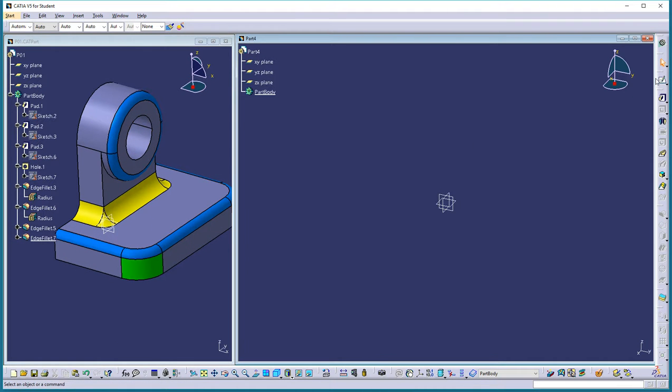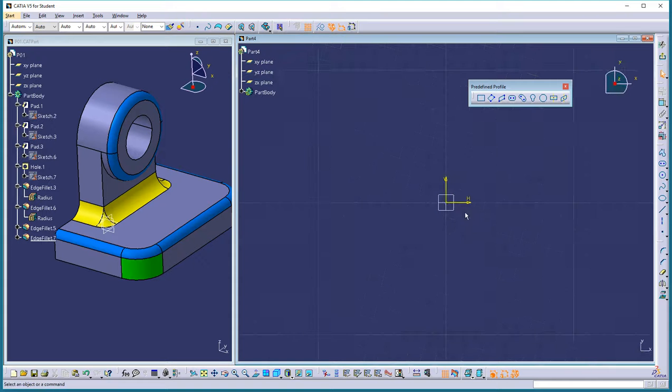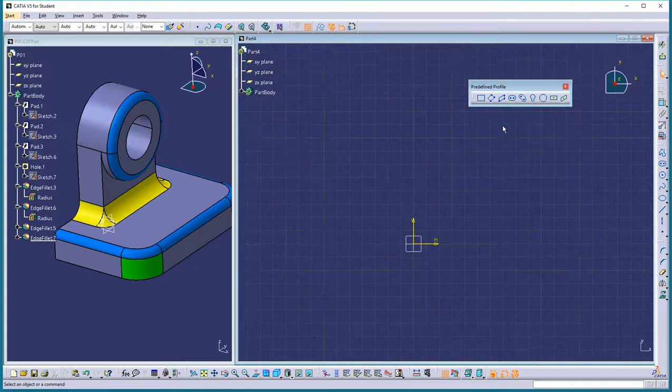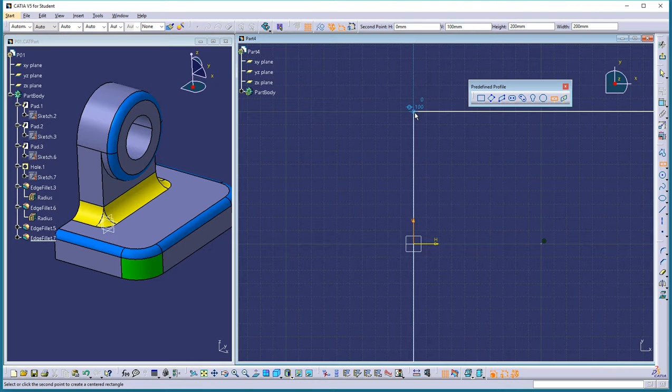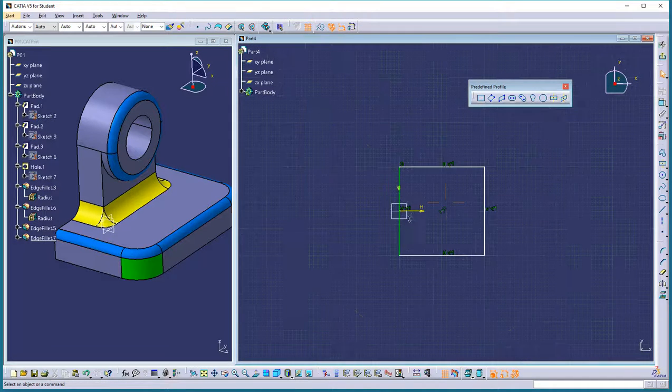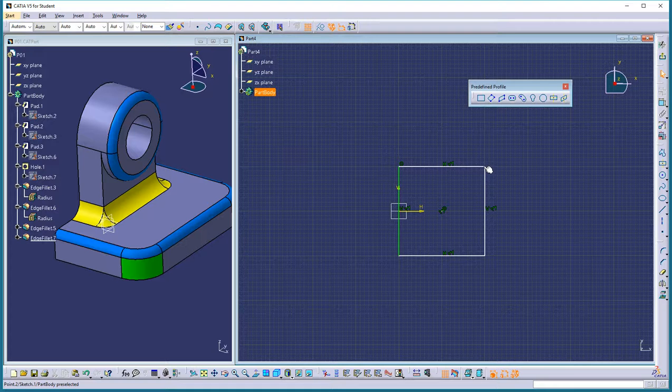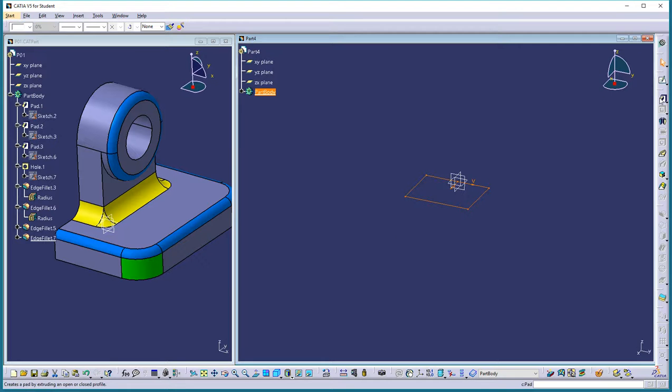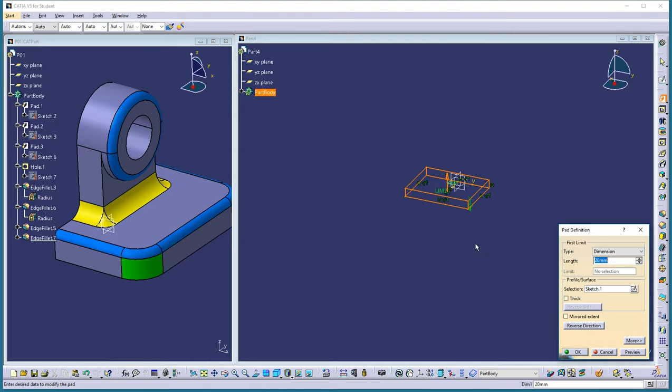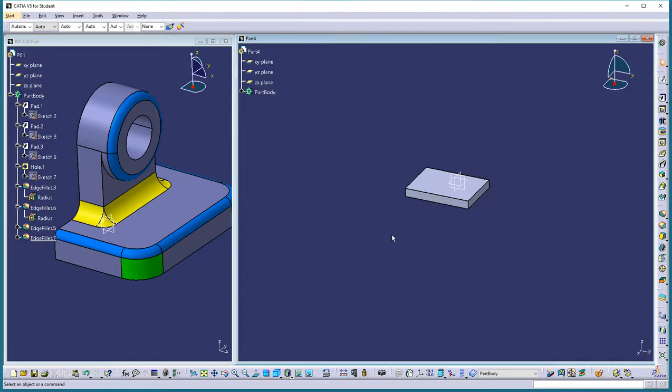Let's come over here. Let's go to Sketcher and let's sketch on the XY plane. Let's sketch that rectangular bottom. So let's pick the centered rectangle, and let's pick, say, here to somewhere up in here. Okay, we're not going to worry about the exact dimensions. We'll make it a little bit smaller, something like that. Okay. Let's get out of Sketcher, and let's make a pad that comes up. That looks about right. We'll just say OK.